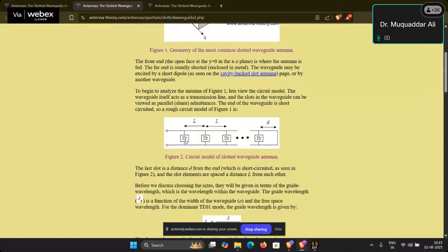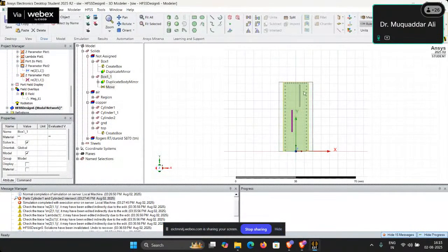That is why we are using this kind of antenna. Now, this arrangement where we place the slot lambda by 4 from the end, and the open end from where we are feeding should have a distance of lambda g by 2 from the center of the slot.